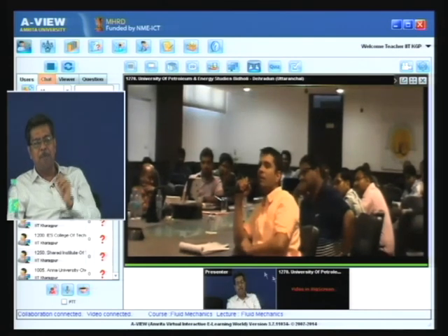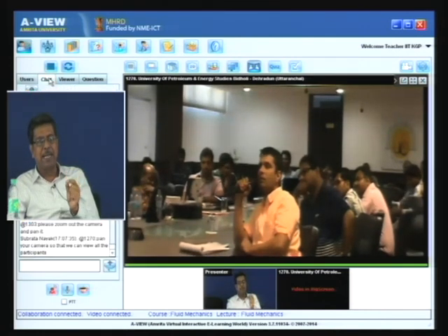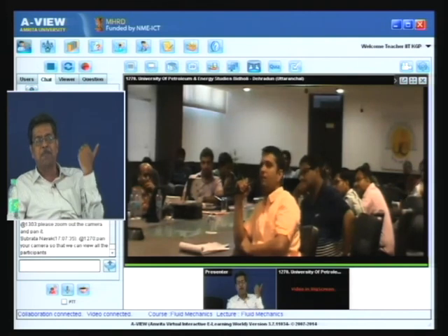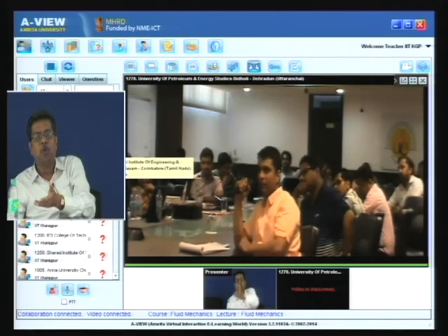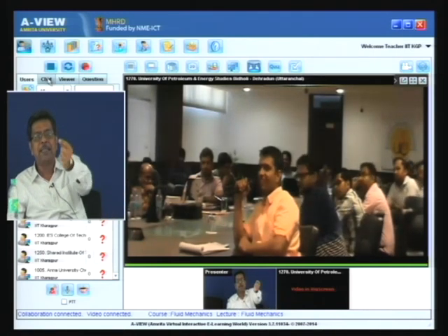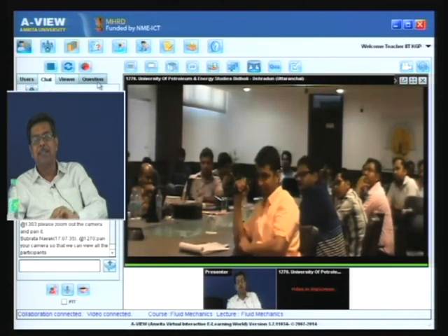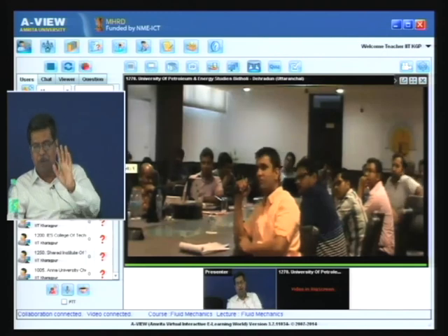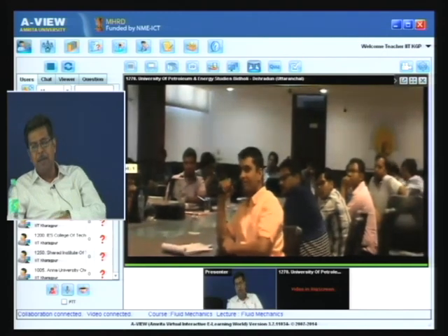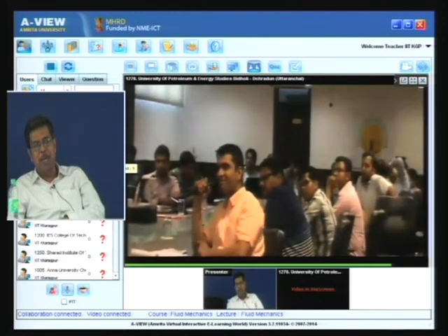In Eulerian approach, we stand fixed at a point and study the particles passing through the points, and that way we tell many people to stand at a fixed point, don't move, and just go on tracking the particles which pass through you, and this way all the people can track all the particles. This is the Eulerian approach. Very well understood and very well explained to the students.